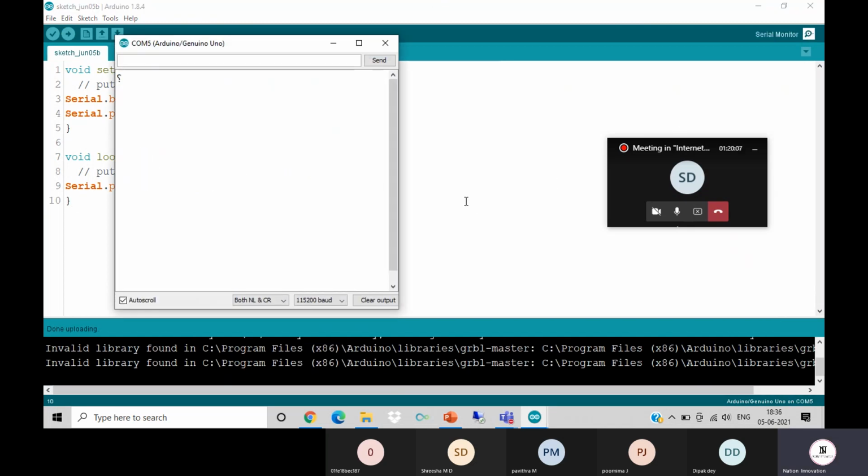Now, when we open the serial monitor, we need to first go to the baud rate selection, and you can see it's 115200, but we have used 9600. You can see it started from 300, and you can use any baud rate you want. The max for the Arduino is up to 115200. The pretty good one is 9600. So this is what happens when we just write.